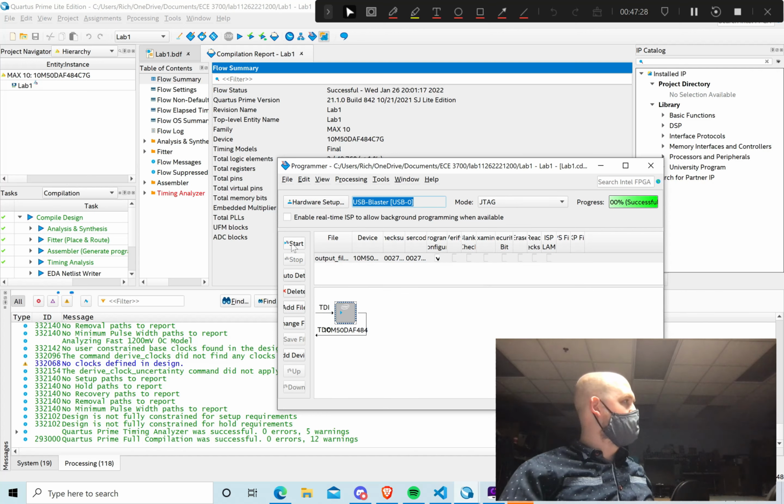Okay. And I'll flip the switches now on the far left. These are my high pins. So if I do 0, 1, that should be an OR gate. So that would mean A0 or B0 seems to work, or A1 or B1 seems to work. So just go through all of your options, make sure that they all work correctly, and if they do, then you're done.